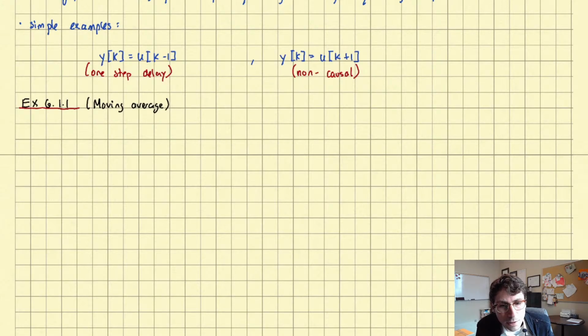Well, non-causal systems just don't exist in the systems themselves. A physical system that you're trying to control will always be causal. I can't think of a real-life system that is non-causal. The non-causal systems that I'm aware of are offline signal processing. And then the question of predictive control. Someone else has asked me about this. We don't cover it in this course, but